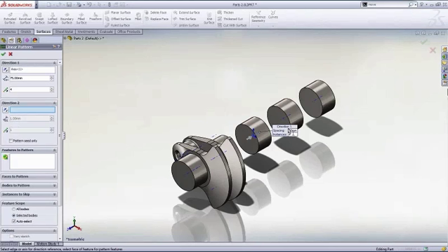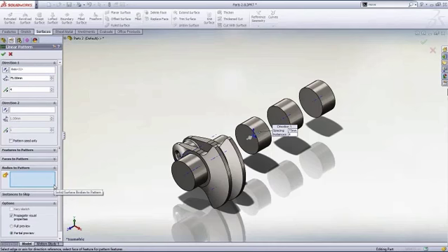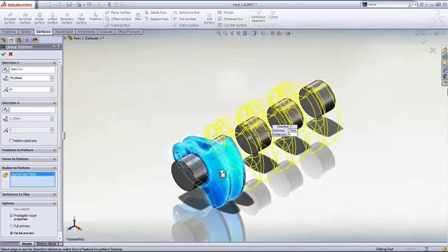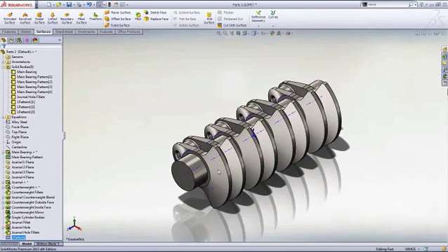Now here's where multi-bodies differ from normal features. In a traditional pattern, I would need to select all the features required to create this. But if I instead expand the bodies to pattern selection, I can choose all that geometry in one go, without any need to worry about which features were used to create it.